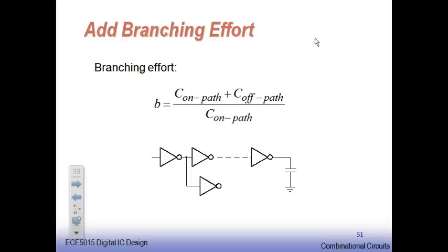You understand? I go for taking a 64-bit data and I work out of the 64-bit data a particular path I have, and for that path I want to calculate across one gate flow. One bit I am taking, how the one bit transits through from the input side to the output side I need to take. So in such a case, I will go for taking into account this path, and also while driving my path which is under consideration, I should also take into consideration the other paths which were driven. So I need to take into account the branching effort.